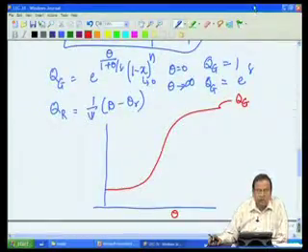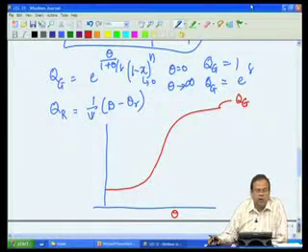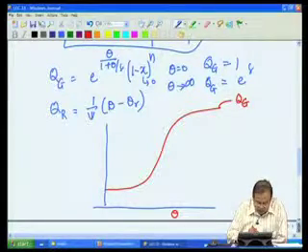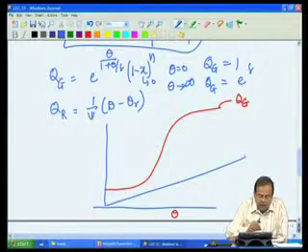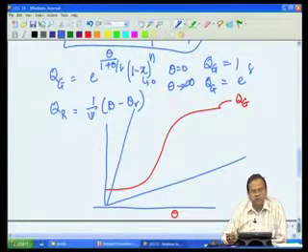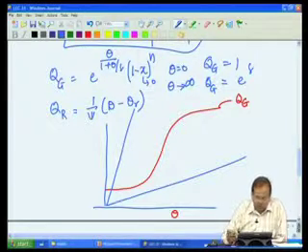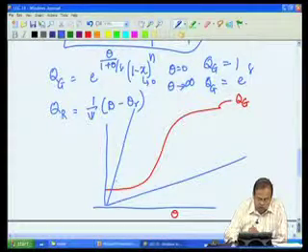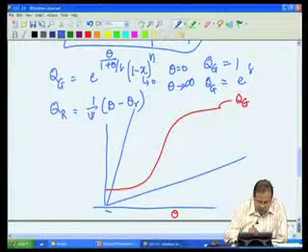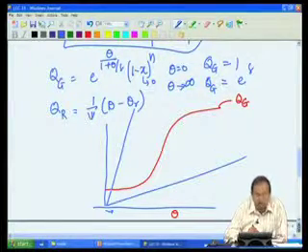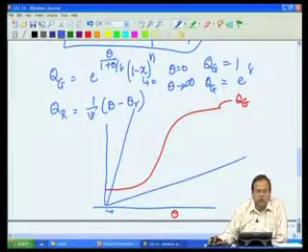So, what happens is when the psi value is very high, that means the heat generation term is much higher compared to heat removal, we have the operating line, which let us show by a different color, of this nature. And on the other hand, if psi is a low value, then we have an operating line of this nature. So, we last time saw what happens if your operating line has a low value of psi, then the slope is very high, and as temperature is increasing, the difference between the generation and the heat removal is progressively decreasing, and so we will have an operation where temperature is more or less constant.